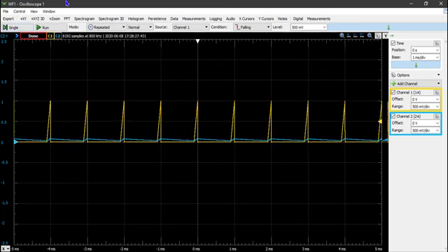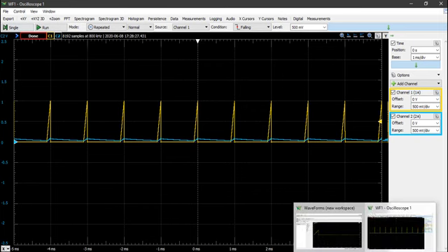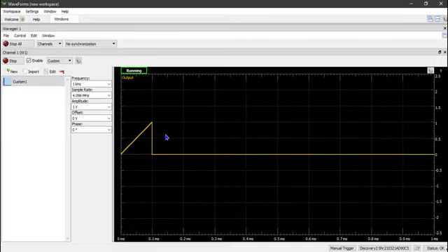So, actually, I skipped a certain part of the instructions, which is why we see that keep repeating. I created the custom waveform, but I still have to configure it in this menu. Since the ramp is only going to be on for 5 milliseconds, the period is going to be 50 milliseconds, which means that we're going to have to use a frequency of 20 Hertz, and that comes from your lab handout. So let's change the frequency to 20 Hertz.